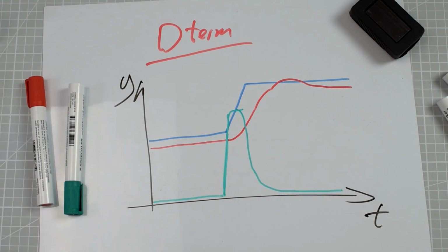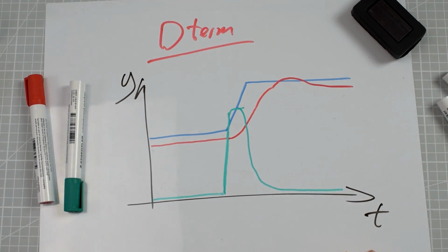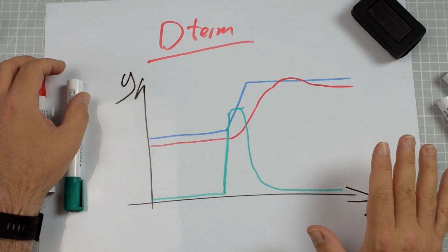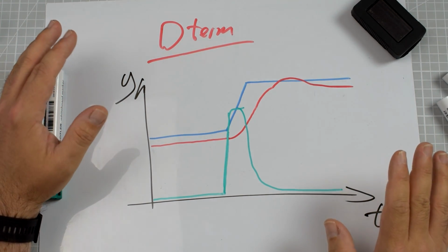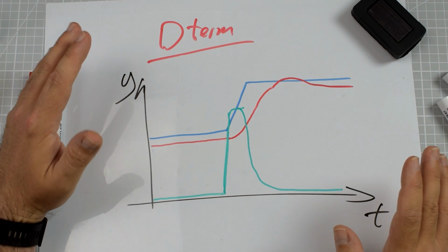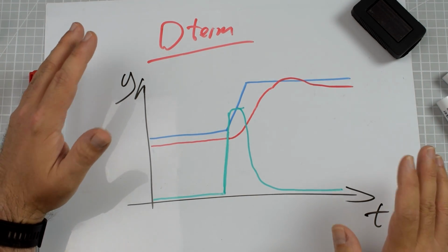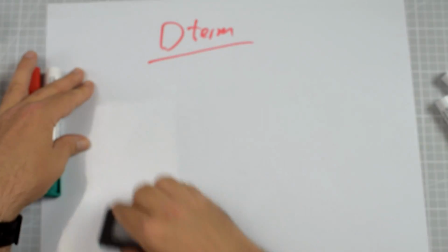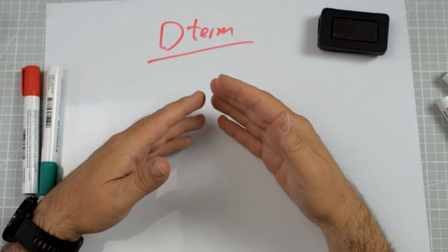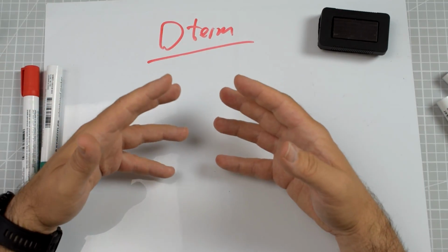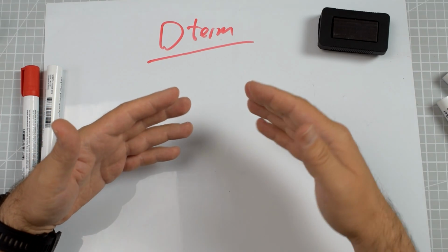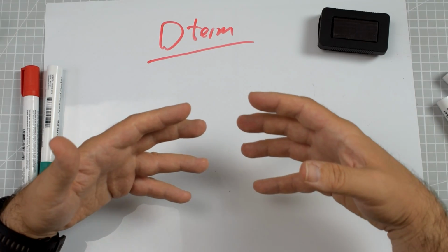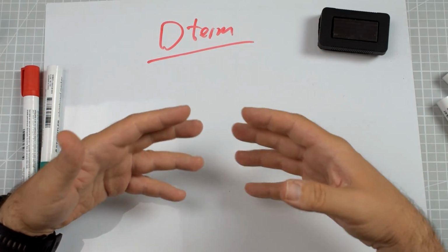This is why modern flight controllers are using different approaches to how to compute the derivative, so that the derivative kick is not that visible and does not affect your flight that much, and still you have a good dampened, smooth response of the whole setup, and yet the movement of the sticks has an impact on the movement of your quad.